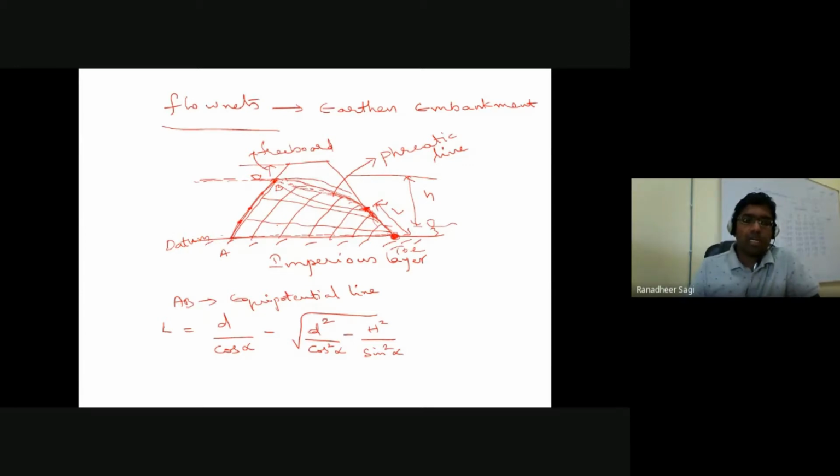So certain information is indicated. Alpha is nothing but the slope of the embankment's downstream sloping surface, the angle made by your downstream sloping surface, that angle is alpha, whereas this angle we call beta. So you have notations for what each of those terms represents. Once we understand how the flow net diagram is to be constructed for the earthen embankment, the rest of the procedure is the same.